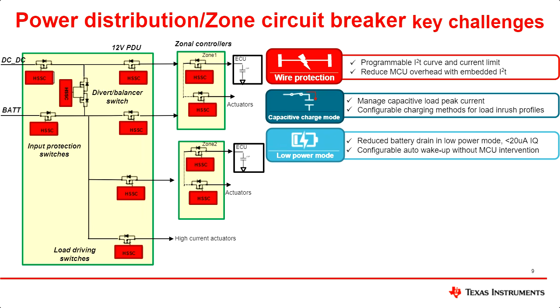One other important challenge here is, since we are directly replacing the melting fuse, the IQ of a melting fuse itself is zero. So that's where we need to make sure that our devices are very low IQ, especially when the car is not running on the engine, it is running on the battery. Devices also need to have this automatic load wake up feature, so that the MCU can also wake up from low power mode to active mode.